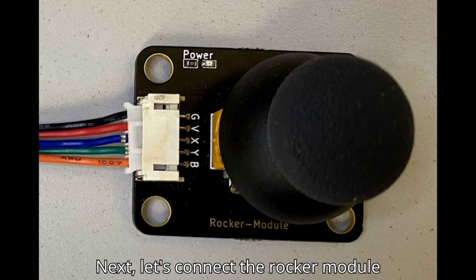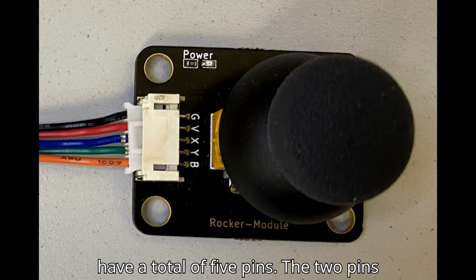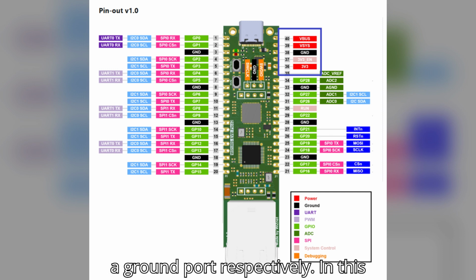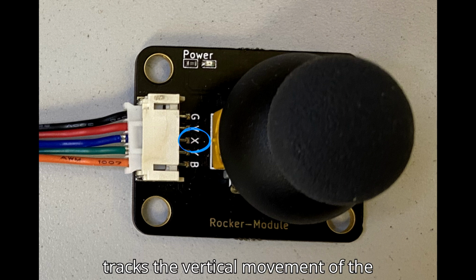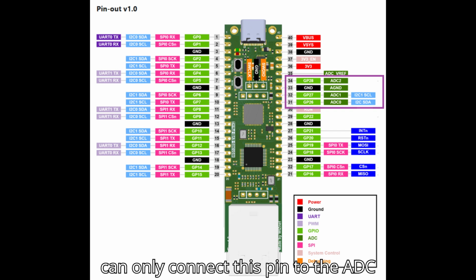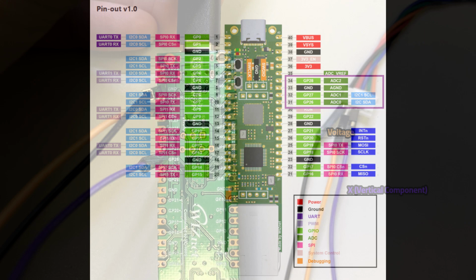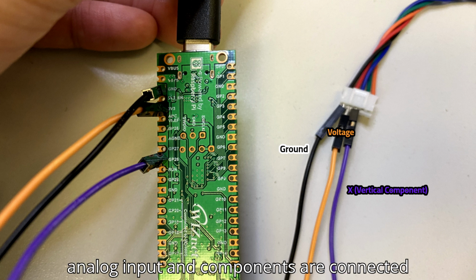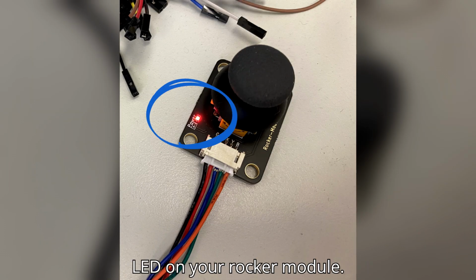Next, let's connect the rocker module with the board. For my rocker module, we have a total of 5 pins. The 2 pins on the top will be connected to the 3v3 port providing voltage to the module and a ground port respectively. In this project, we only need the X pin as it tracks the vertical movement of the rocker module. Since the output is an analog signal, we can only connect this pin to the ADC ports, which are GP26 to 28 from our documentation. In this project, GP26 is used for the analog input and components are connected as follows.